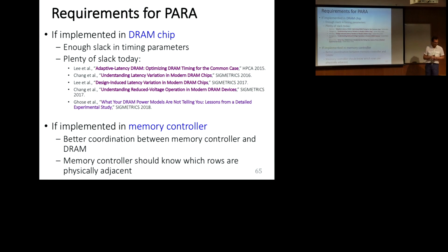If you hammer the same address, why would you ever close the row? Well, in order to be able to do the hammering, you need to close. So you cannot just do activate. You need to activate, pre-charge, activate, pre-charge. So every pre-charge, yeah. Because hammering doesn't happen in the row buffer. You really need to activate, pre-charge, yes. The least you can do is activate, pre-charge, activate, pre-charge. But of course, in real programs, you cannot do just activate, pre-charge. You need to do activate, read, pre-charge. Otherwise, the memory controller gets rid of all of that, right?